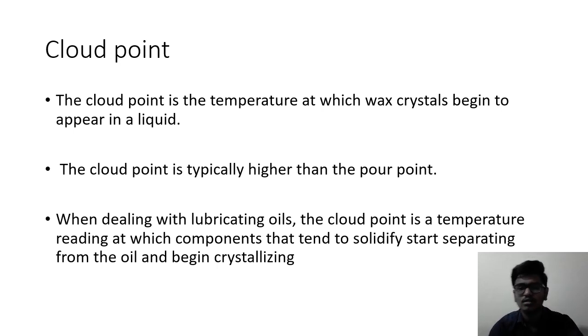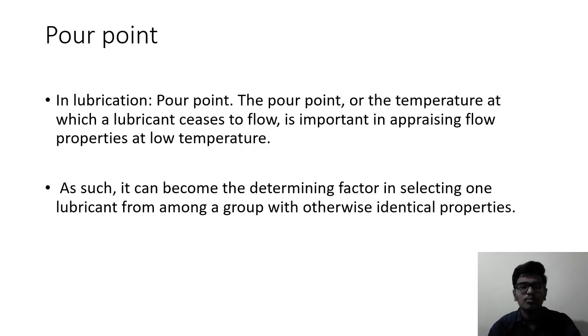Okay, let us see some more. And here the pour point. In lubrication, the pour point, or the temperature at which a lubricant ceases to flow, is important in appraising flow properties at low temperature. As such, it can become the determining factor in selecting one lubricant from among a group with otherwise identical properties.